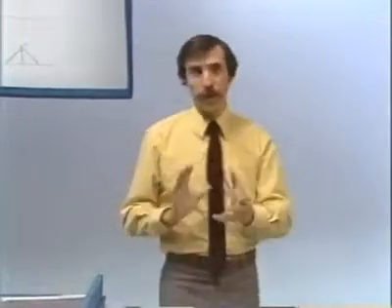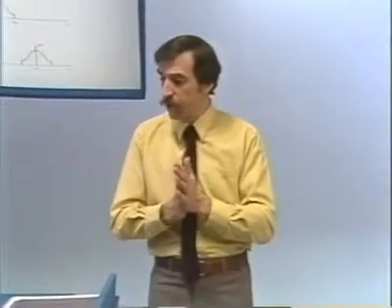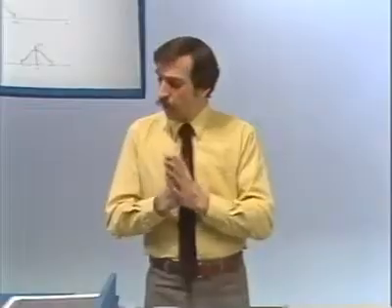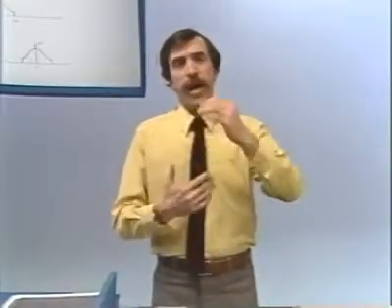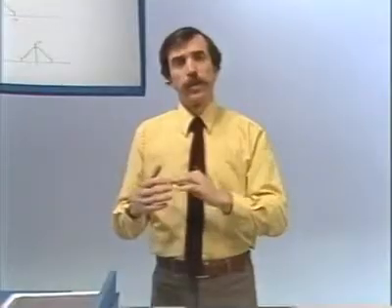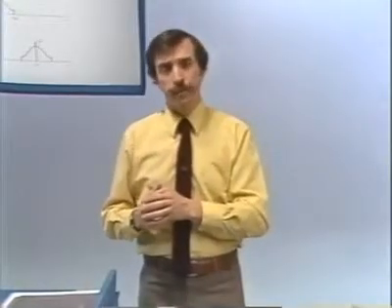And so there's this trade-off, and in fact, one very often represents the trade-off and the associated parameters in terms of percent modulation, where the percent modulation is essentially the ratio of the maximum signal level to the amplitude of the injected carrier.